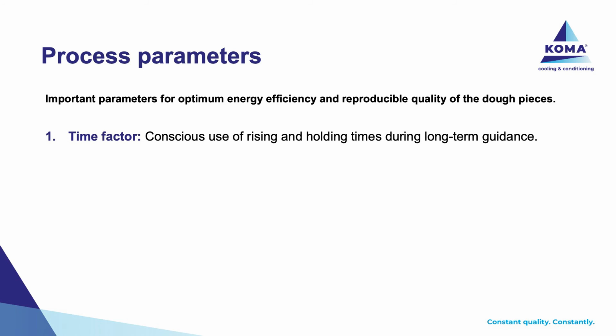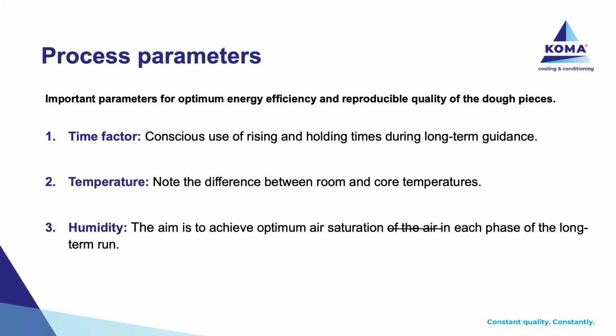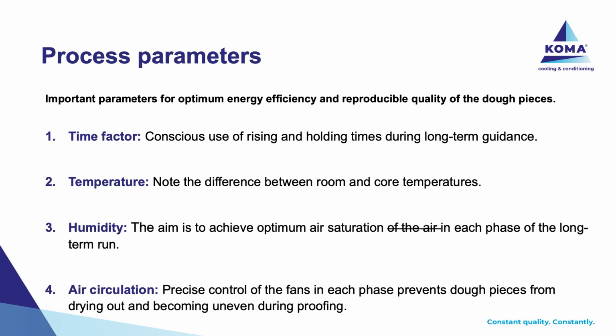Summary. We saw all kind of phases. Important phases in all the parameters is time, temperature, humidity, and air circulation. To be able to get an optimum product quality in the proofing process, you need to verify the most essential parameters for your product. We make sure energy consumption will be as low as possible. So adding humidity, adding heating only when demand in climate is being forced.